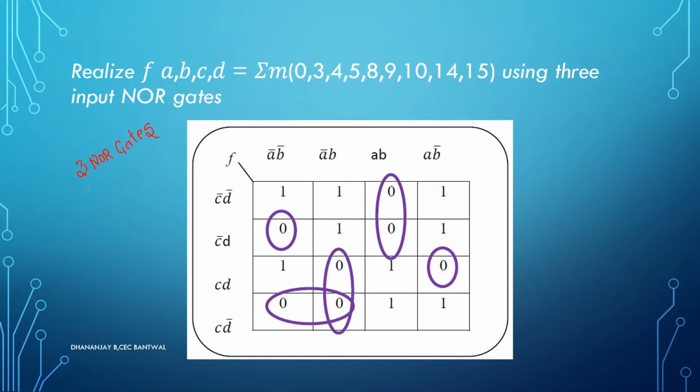So as always, what you are going to do, as I explained, is take a truth table. After the truth table, you are going to take a K-map, normally an easier method when there are 4 variables. After the K-map, you are going to group them. After you group them, you will get an expression. Once the expression is obtained, you will try to reduce the expression to a simpler form. And after the expression has been reduced, you will try to rig up the circuit.